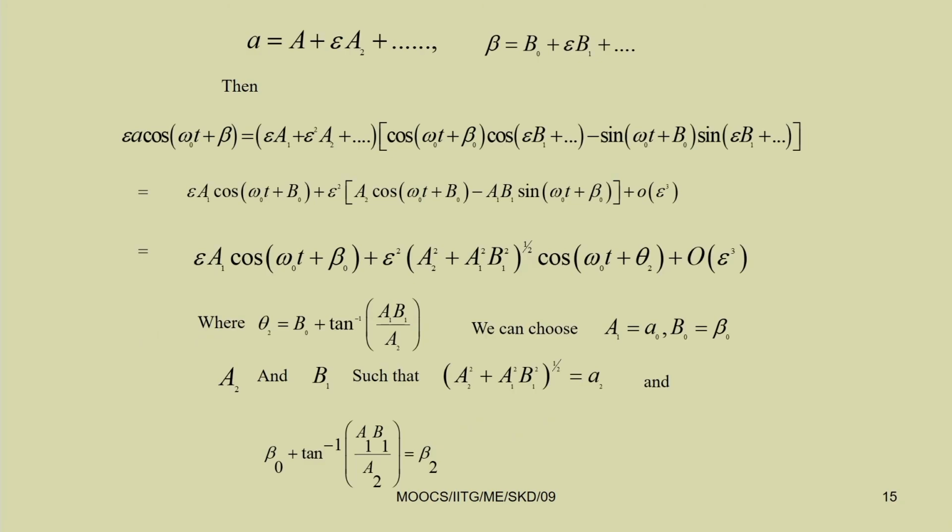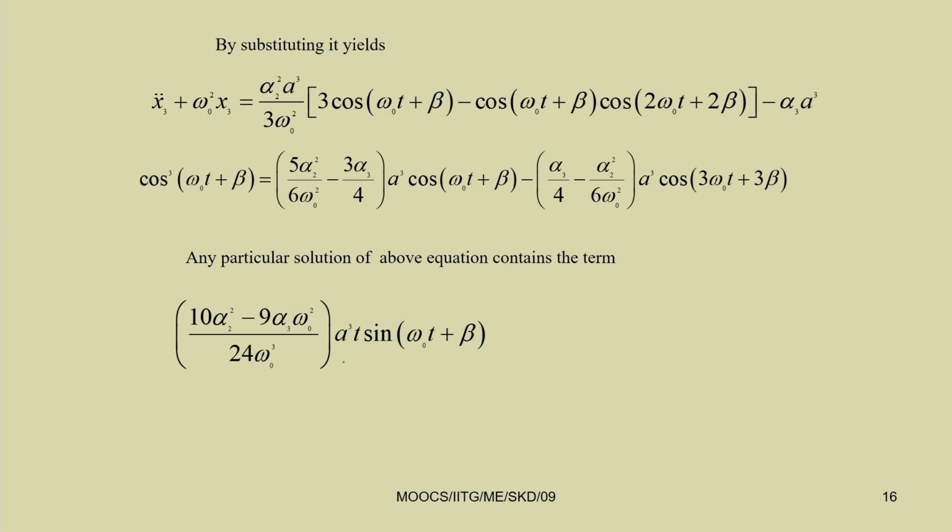So, here you are observing that finally you are getting a solution which is a function of t. As t tends to infinity, this expression, that is x3, tends to infinity also, but as the solutions are bounded, this type of solution is not feasible, and that is why one has to modify this equation or modify this procedure, the straightforward expansion procedure, to find the solution. In the actual case, these terms which involve this t are known as the secular term. So, one has to circumvent or work in such a way that this term has to be eliminated.